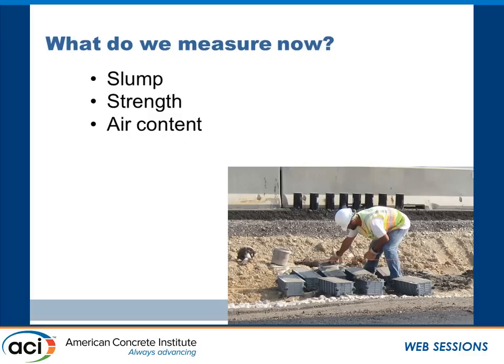Okay, the other one I really enjoy about this image is if you have a look, if we talk about quality assurance, at least one of these beams is twisted. So is that going to give us a false low or a false high result? False low. So while the concrete's perfectly good, the data point coming back is going to be low. The contractor's not going to get his bonus on this day. Yippee.